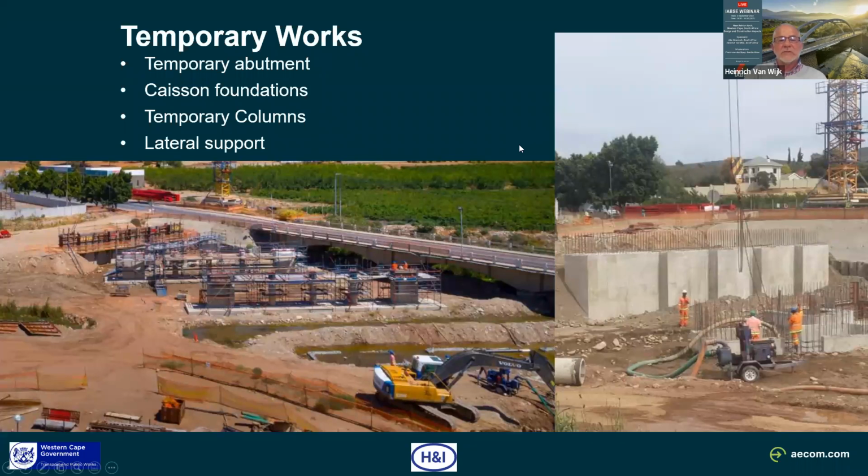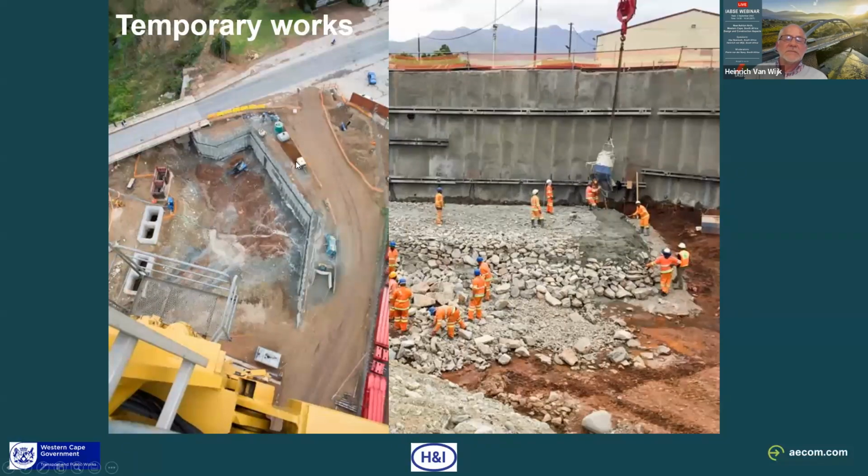Then we can go through a few other parts of the temporary works. In a sense, the temporary works were very extensive. We initially foresaw that the contractor would use steel heavy-duty columns, but they felt that concrete, demolished afterwards, was more efficient. So that's part of the temporary works being constructed. They used temporary caissons in the river to construct the support structure. We had shoring around the abutment locations, because we had to go down quite deep, as you can see there, using the laborers as a scale factor, and that had to be extended when we went across to the new foundations.